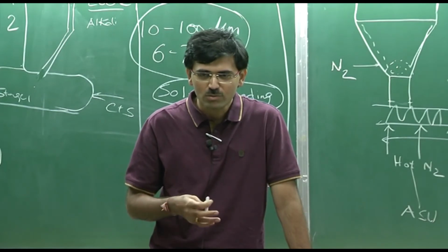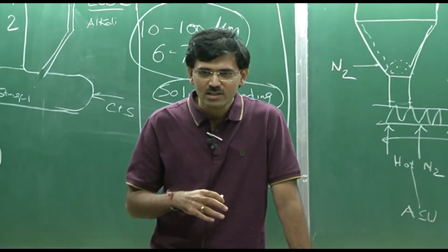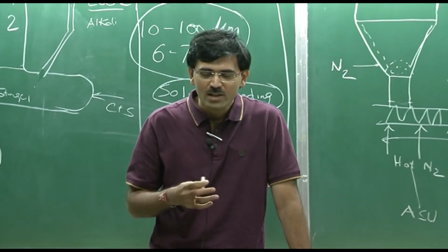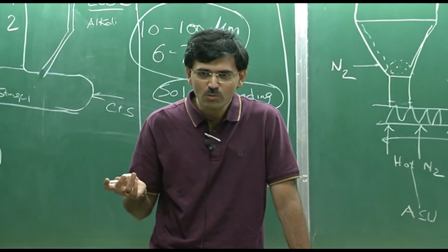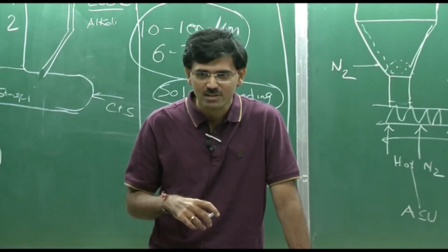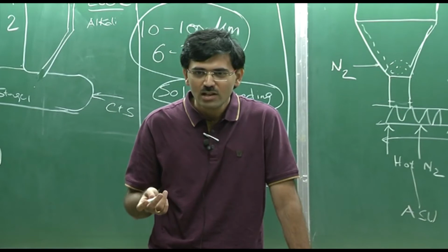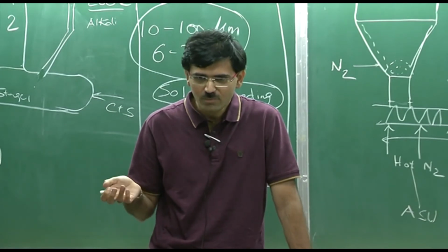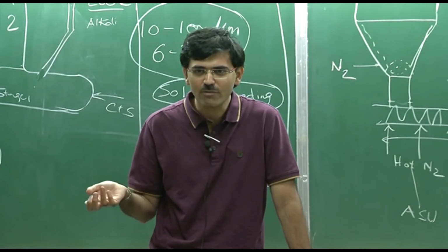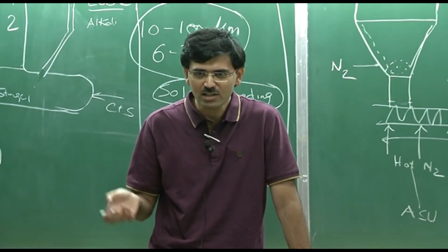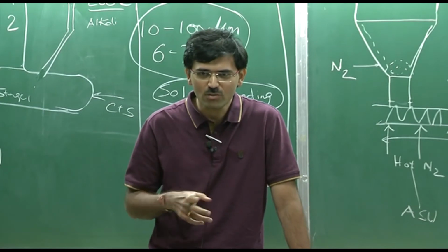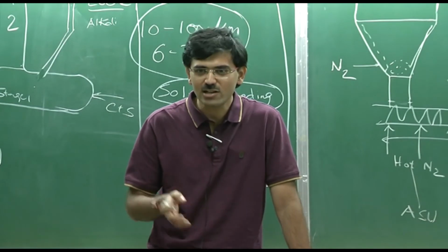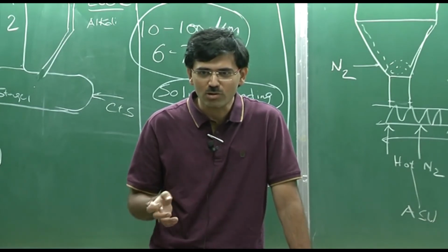If EGR is attempted, the carbon dioxide will rise, and for the membrane, the idea was to use air as a sweep gas to quickly disperse whatever carbon dioxide is produced, so that carbon dioxide permeation happens at an accelerated rate. That was the whole concept.